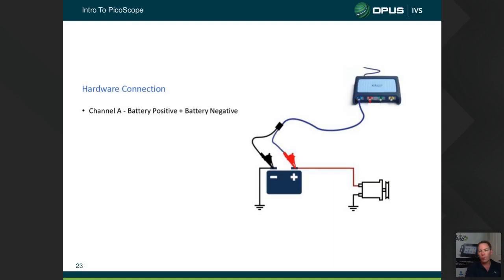Now, if we look at a four-cylinder, we've got a firing stroke every 180 degrees, you know, 2 up, 2 down. As they spin around 180, we'll have another firing stroke. So what will actually happen is the alternator will spin fast, slow in relation to the crankshaft in those power pulses. And what this is looking at, because it's so sensitive, it can look at the voltage increase and decrease for each power stroke, and it can measure it for us.